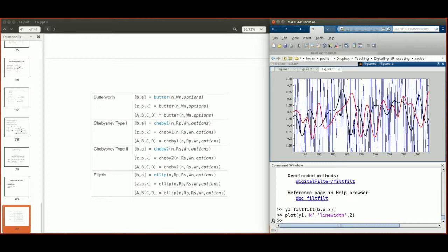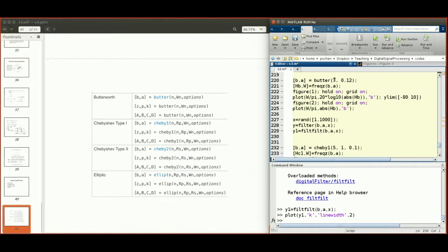But you can also see that if you compare the black waveform with the red waveform, they are still slightly different. The reason is that the black waveform has a narrower bandwidth, because you are applying the same filter twice. The amplitude is being applied twice, so it's narrower, right? It's equivalent to a 14th order Butterworth.